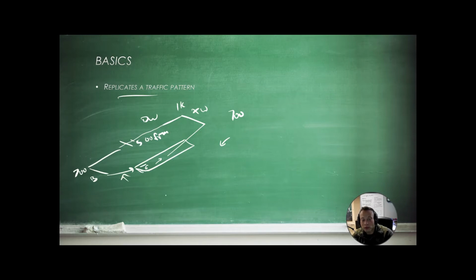And of course, on final, we want to be making sure we are configured to land: landing gear down, flaps set, trimmed off or whatever. By this point, we should have conducted our pre-landing checks. I like to do them here on the downwind, and then again on final, just in case I missed something. Don't want to be landing with our gear up. So that's the basic traffic pattern.